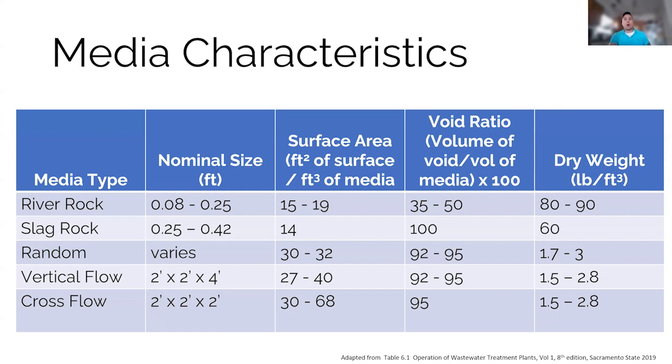And it's used for lower hydraulic rates that can have more time to be exposed to the bacteria that are going to be removing the BOD. Now, for the most part, though, these are typically arranged together. A lot of times you'll have your vertical flow that leads to your cross flow. So you get a high amount of treatment, and then you get a more targeted treatment for this media.